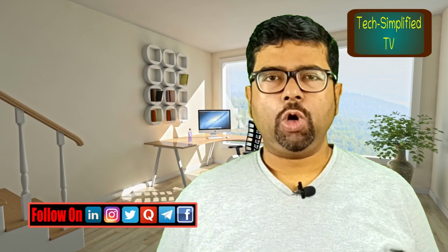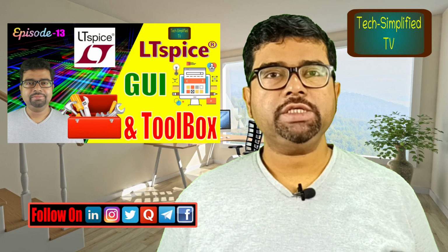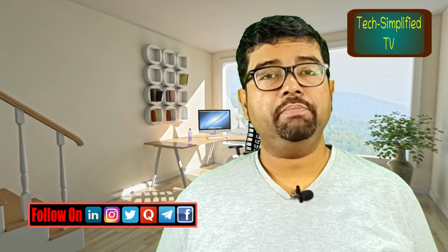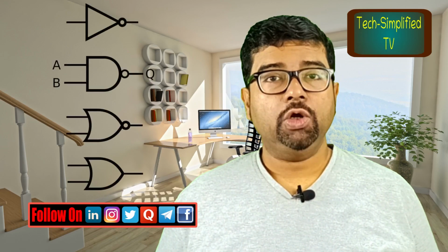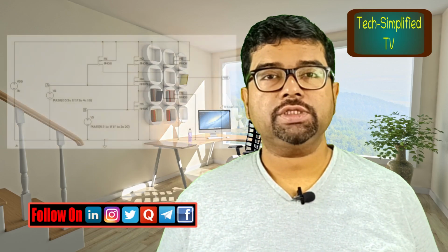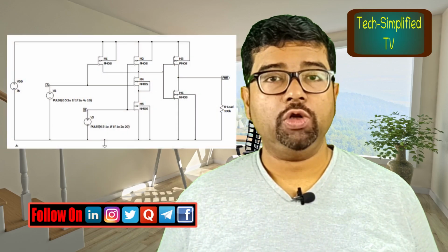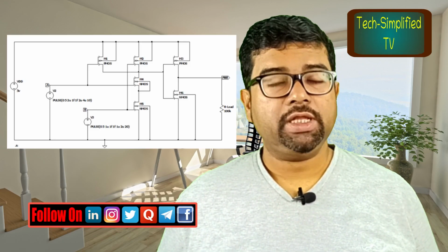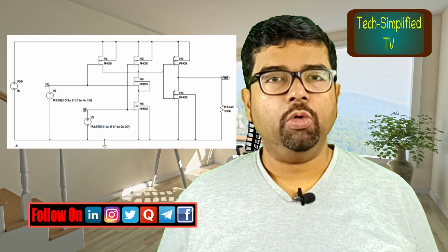Hi folks, you are already familiar with the LTSpice UI and toolbox. In the last couple of episodes, you have become familiar with the basic CMOS circuits like NOT, NAND, NOR and OR gate. In this episode, we will construct a CMOS AND gate using 6 monolithic PMOSFETs and NMOSFETs, where the PMOSFET has double the area of the NMOSFET for mobility balancing.